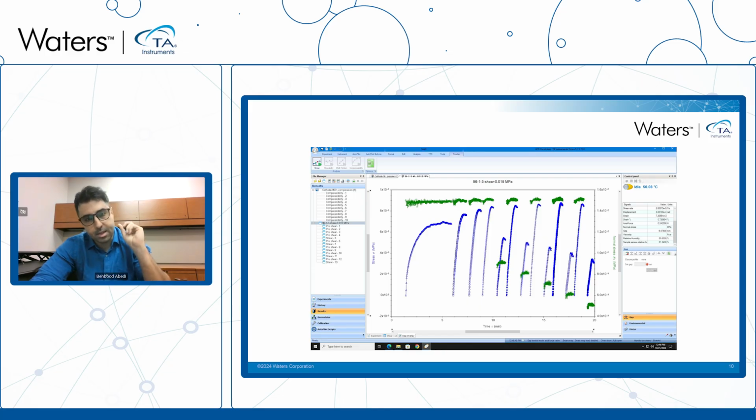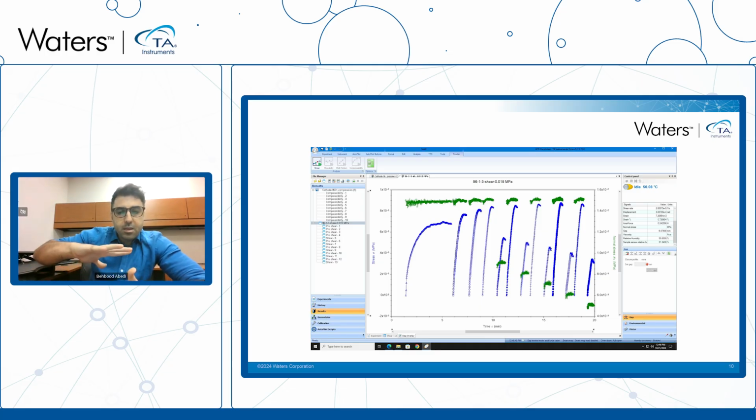So we have the consolidation stress, then we reduce the normal stress to a value, and we apply a very low shear, like 10 to the minus 3 radian per second, and you raise the stress until we have the yield point. So you got the yield point. At different normal stresses, like here at 5 different normal stresses, you have 5 different yield points.